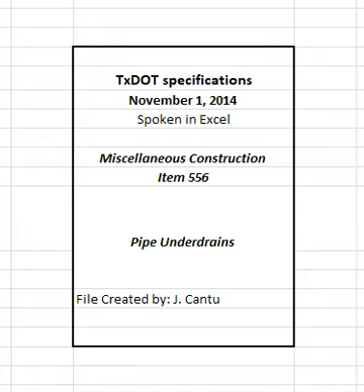Join plastic pipe in accordance with the manufacturer's recommendations. Do not use tar paper strips. Obtain approval for pipe placement before placing filter material. Place filter material at least 12 inches above the bottom of the pipe or as shown on the plans. Do not allow filter material to displace the pipe.